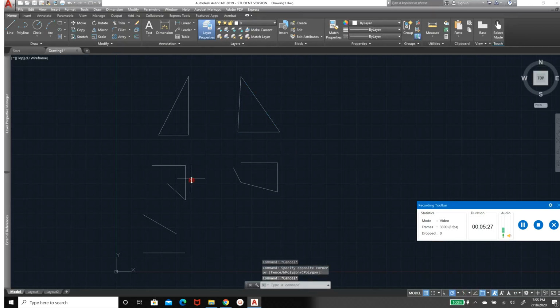And so when you're doing that with just line instead of polyline, and let's say I go from here to here, instead of selecting this entire thing, it'll just select the 2 lines that it's touching, as opposed to if I were to do it here, it would select everything. So that's the difference between line and polyline. For that reason, polyline is a lot quicker to work with in a lot of ways, and it's the one that I prefer to use because it's all joined as one object already.